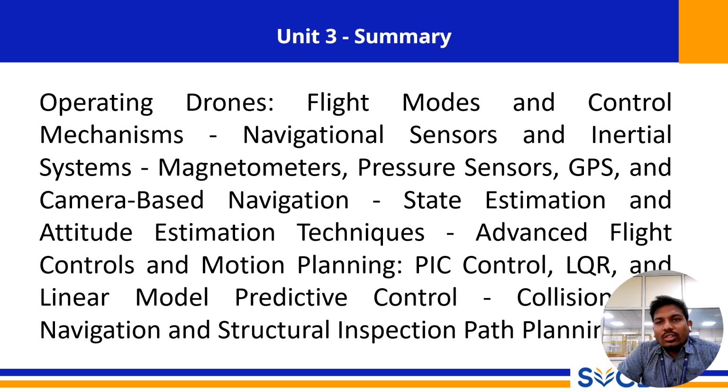An absolute pressure sensor, or a barometer, measures ambient atmospheric pressure to determine the drone's altitude above the ground. Different pressure sensors, often part of a pitot-static system, measure dynamic pressure to calculate the drone's speed relative to the air mass, which is crucial for efficient flight and stall prevention.